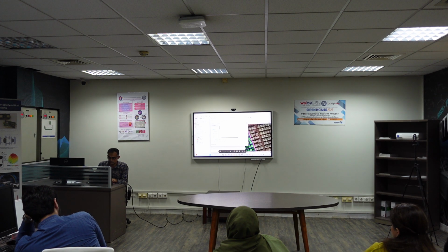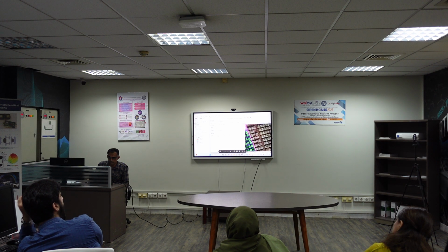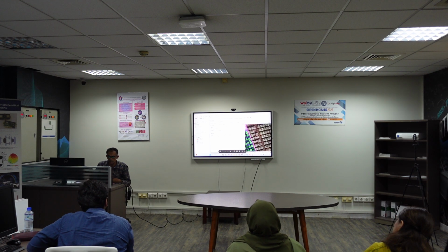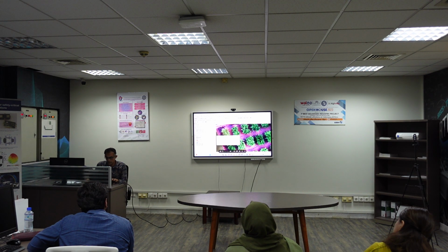We'll just give it a name. Select it. Let it be a polygon, and you can also assign a particular geographical coordinate system, which is already there in WGS84, but we can always change it. So using this, come to this editing mode, put a polygon here. Now you see.